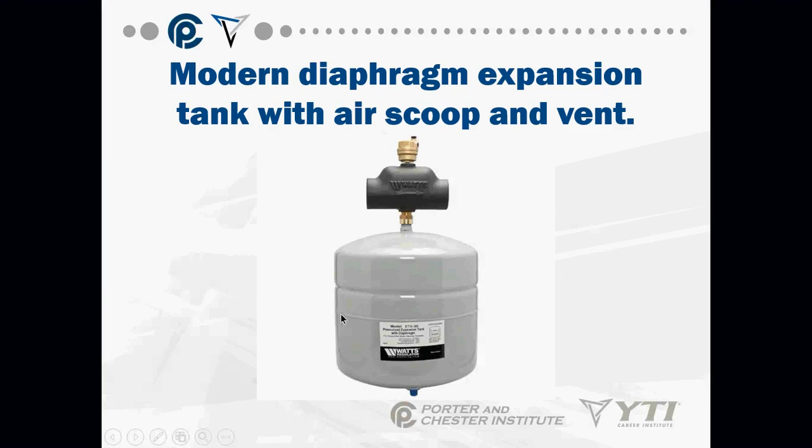Okay, right where this weld is on this picture is right where that diaphragm is going to be. So everything up in this section will actually be filled with water as we fill that boiler up. Everything down here will be nothing but air. As the water fills into this expansion tank, that diaphragm will expand and push down on that air cushion. And that's how we are able to allow for water expansion in a boiler.